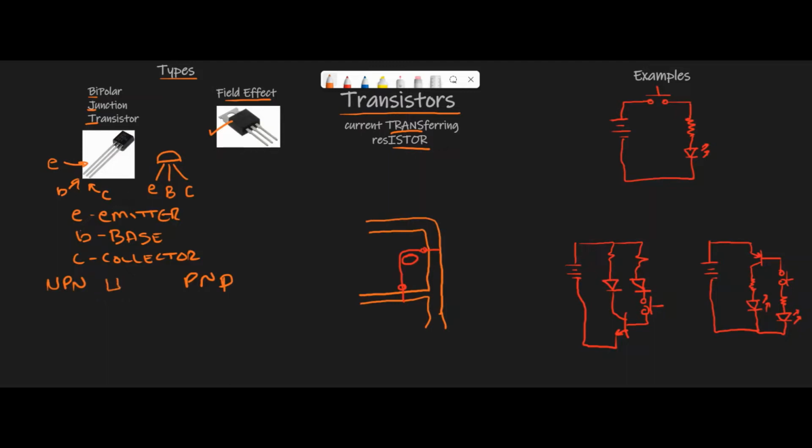So, as you would think, there is an N-type, and then a P-type, and then an N-type. 1, 2, 3, and there's your 3 pins for your NPN. And the same thing over here, except this is a P, this is an N, and this is a P. Same 3 pins. So this is an NPN, and that's the silicon structure of what's inside of this package, and a PNP type, which is what's inside that package.